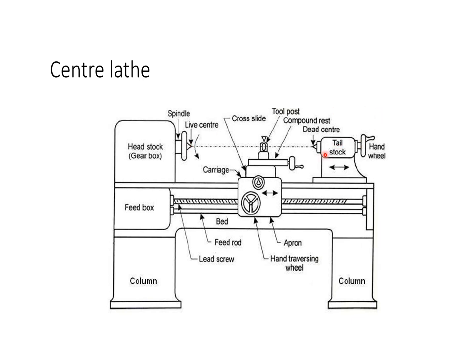Then the tailstock. The tailstock can be used to support the end of workpiece with a center to support longer blanks or to hold tools for drilling, reaming, threading, or cutting tapers. Also, it can be adjusted in the position along the way to accommodate different length workpiece. The tailstock barrel can be fed along the axis of rotation with the tailstock handwheel.